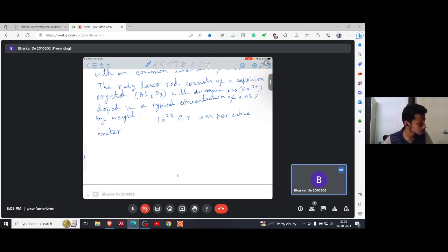The laser is a 3-level system and therefore has a much higher pumping threshold than a 4-level laser system such as Nd:YAG. However, the ruby laser has an exceptionally long upper level lifetime of 3 milliseconds, which gives it an unusually high energy storage capability. Pulse energies of up to 100 joule are possible, although the pulse repetition rate is low, 1 or 2 pulses per second, which limits the average power. This limitation is due to the excess heat produced by the high pumping flux required to produce laser output.